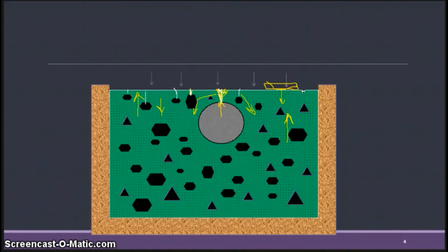Okay. So these aggregates are pretty deep, so it might be possible that the deformation will not lead to cracking, but wherever you have aggregates which will support the concrete above it, that is, they will not let the concrete subside in this region, because the concrete on the side is subsiding, it's going to form stresses on it.